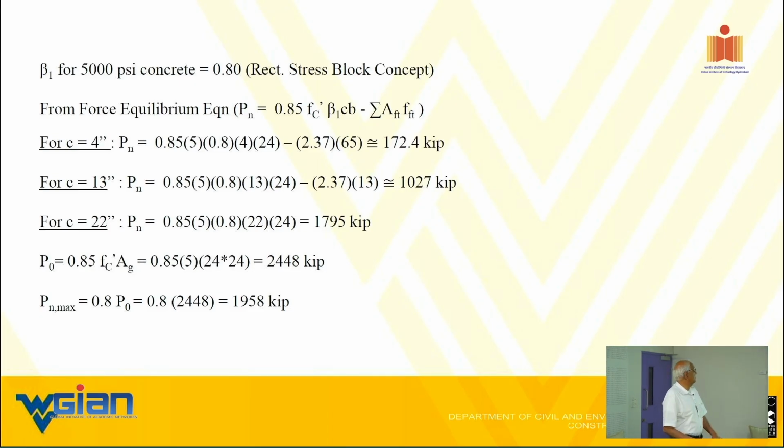So it is a function of f'c, but it's a highly convoluted approach, and you do need this for design, whether it is steel or FRP. The numbers may be different, but the procedure is the same. It is a little bit more involved with FRP because there are a couple more complicated empirical equations, but the philosophy is the same. The reason I keep saying that is, don't be scared about it. Most of you are aware of how to design these with steel, so it's a matter of tweaking it for FRP.